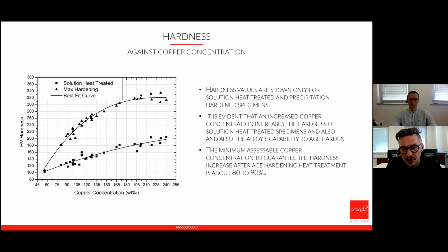If you want the same color in 18K red gold, you cannot have the temperature, because it means you have 90% copper in the alloy. To have the same color, you should put 90% copper also in the solder, which means no soldering phase. So we have it, but it's not the color that people usually expect.